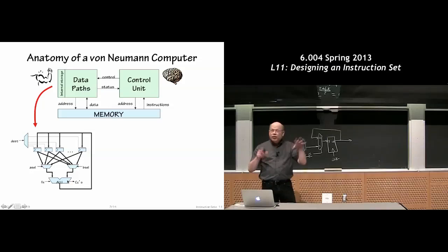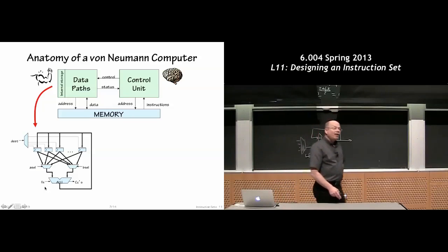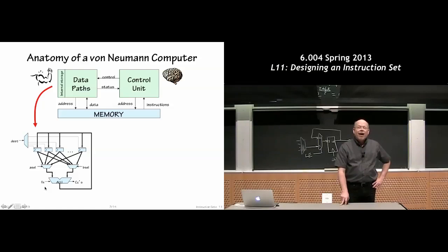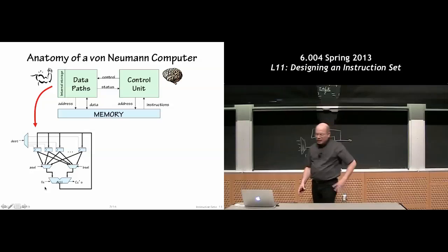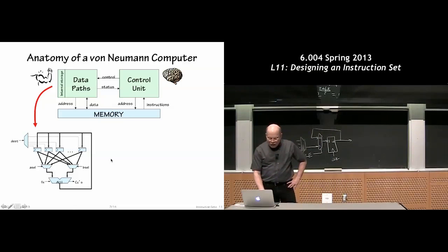And in fact, you can choose the same register, so you can operate on 2 copies of the same value or different registers. We have to figure out what function the ALU performs, and in fact, you already designed a unit that takes a 5-bit opcode, takes 2 operands, and does something to them and produces an answer. You produce a data value that's out, and you also potentially produce some condition codes, some Z, V and N bits and things like that. Okay, and then the final thing that we need to do is specify which one of these registers here will get the resulting value.